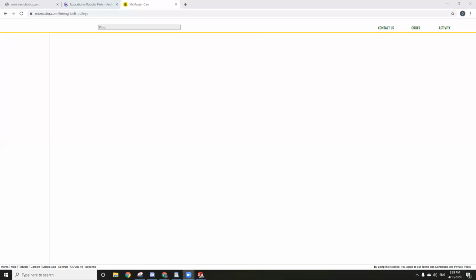Okay, I had a question in chat. So do you want us to use that kind of reference tree whenever we're making our pieces for the Catathon? Yes. I don't want you to dimension everything out. So rather than dimension all the different holes or use a linear sketch pattern, you'd rather us do a square and then have the construction line still there? A linear sketch pattern's fine, but I don't want them to have to see a bunch of just dimensions.